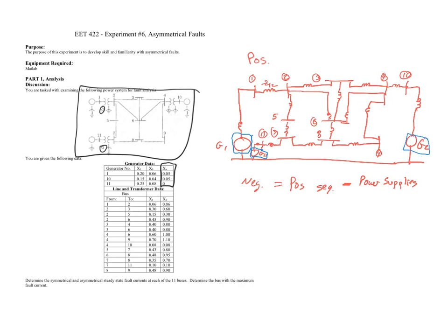But because there's no negative sequence data provided in the table, we're going to assume that we have x1 equal x2, so no data. Don't forget these are x values, so when you're setting up your matrices, these should all be multiplied by the j term.